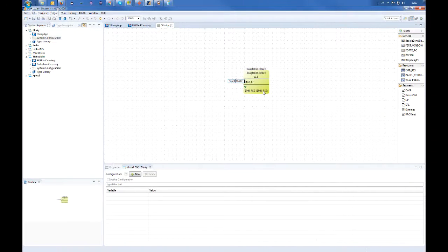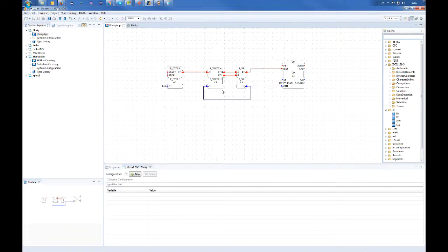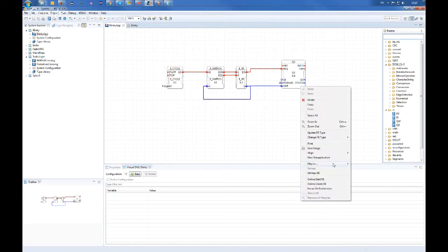Our device, if it's working, should be located at this IP address. By default, 4diac devices, or IEC 61499 devices, listen on port 61499. And you see we already have some resources here.